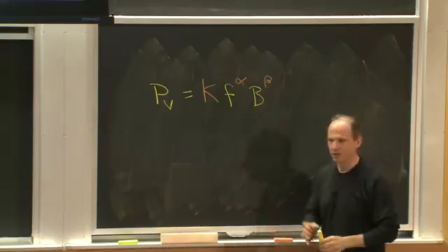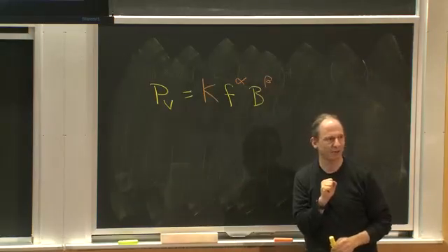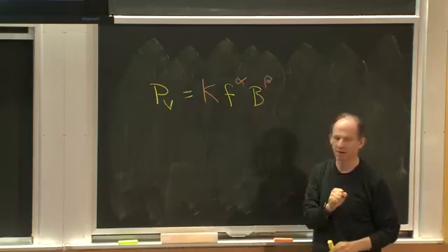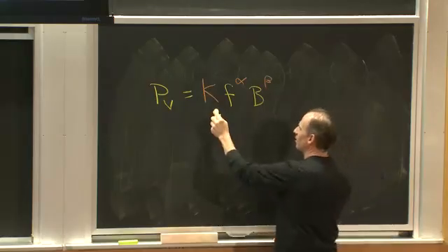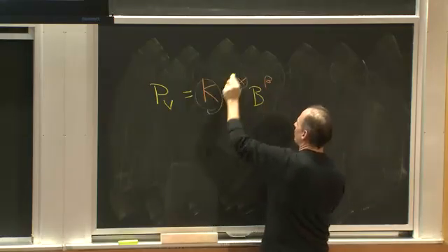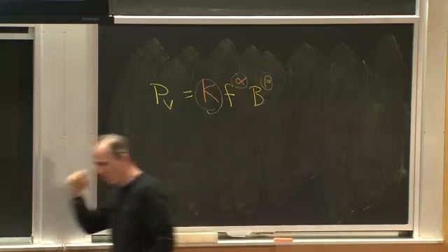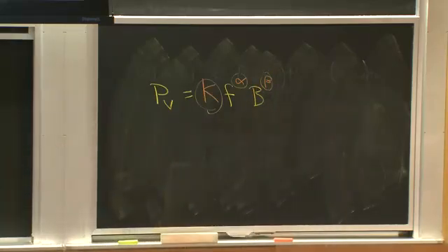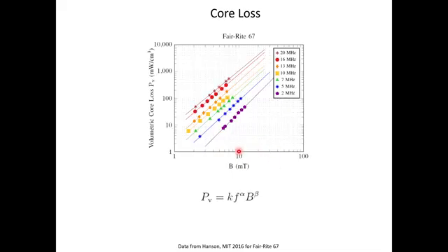They collect data like that, figure out the core loss from measurements, and give you K, alpha, and beta, or a plot. You look at it and say, this is a high frequency material, I'm going to put 10 millitesla through it at 5 megahertz, and I have 500 milliwatts per centimeter cubed, and that's how you calculate it.